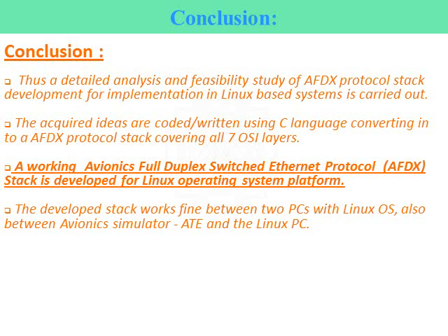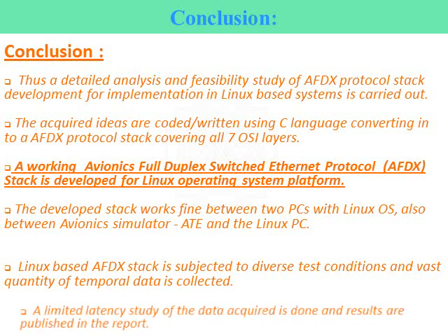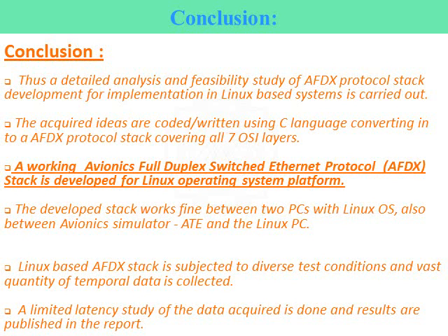The developed stack is checked extensively between two PCs and aircraft test equipment. Conformity with the standard ARINC 664 part 7 has been carried out. The Linux based AFDX stack is tested and various temporal latency analyses have been done. The latency analysis for RX and TX has been done in a limited way.